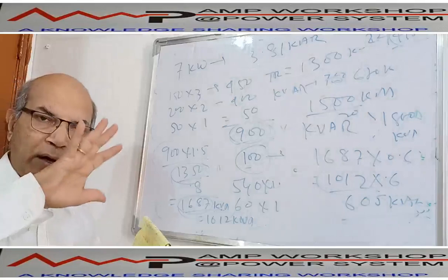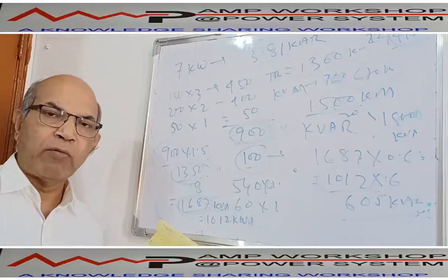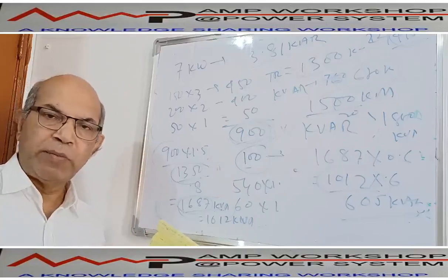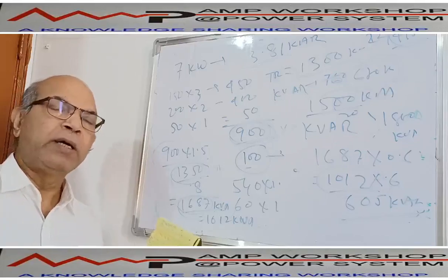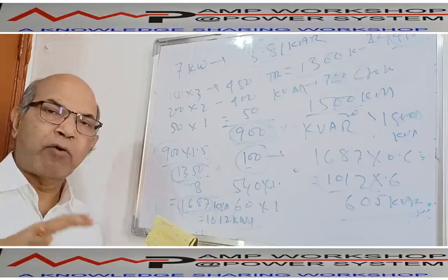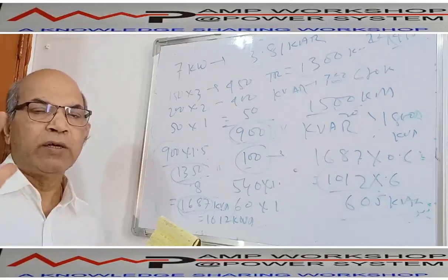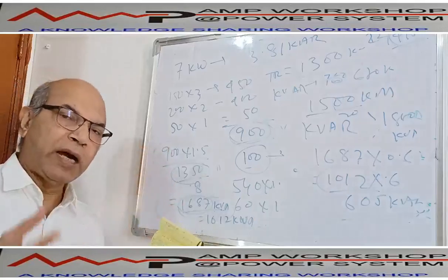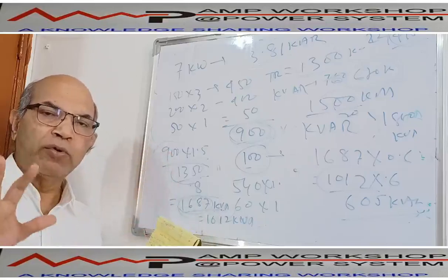So in a particular locality or housing complex, there are many apartments; if they are different types of apartments then the power requirement is different, but for each apartment we can calculate the maximum demand this way. Then summing the maximum demand of all apartments, we get the total sum of maximum demand. Using diversity factor, we can calculate the total maximum load coming on the system. That should be catered by the transformer. In addition to this, we put 20% margin.